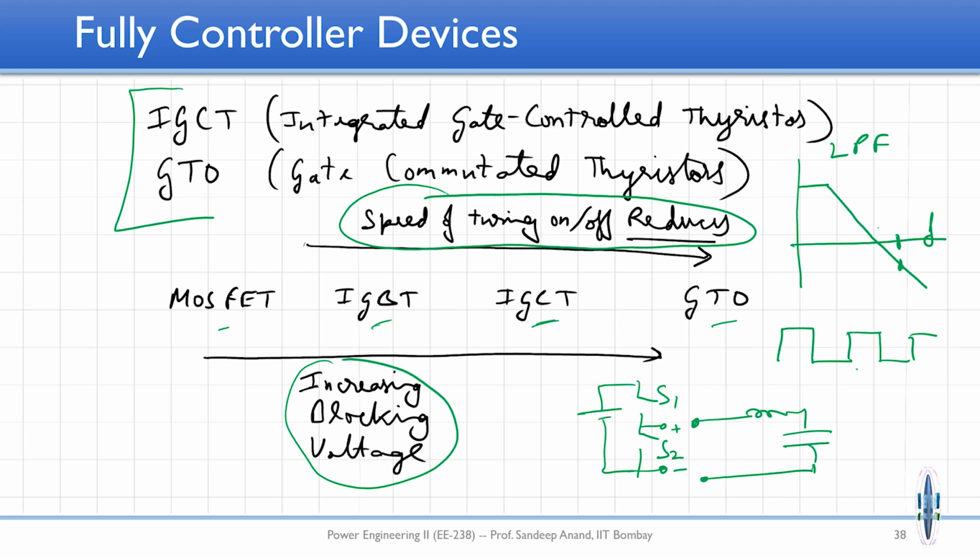If you pass this signal through this low pass filter, and the frequency of the signal is, let us say, F1, you would like F1 to be somewhere here, so that you do not allow F1 to pass through and you only allow the DC component to pass through. This is the gain. You have seen these kinds of gain versus frequency plots. This is a second order low pass filter. It is designed to stop F1 from flowing through it and to allow DC with unity gain to flow through it, so that after this you get an almost nice DC voltage. Is this fine so far?